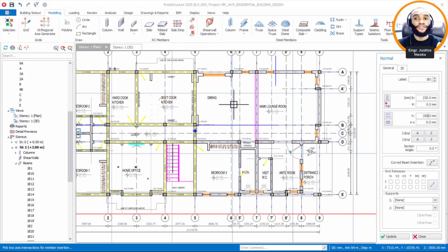Okay, that's fine. So with that now, if we have 300 plus 120 slab depth, that's giving us what, 320, sorry, that's 420, right? So yeah, 420 basically, that's what is meant to be our depth. Okay, what if we use a slab depth of 100 on this particular area? So 100 plus 300, that's 400.